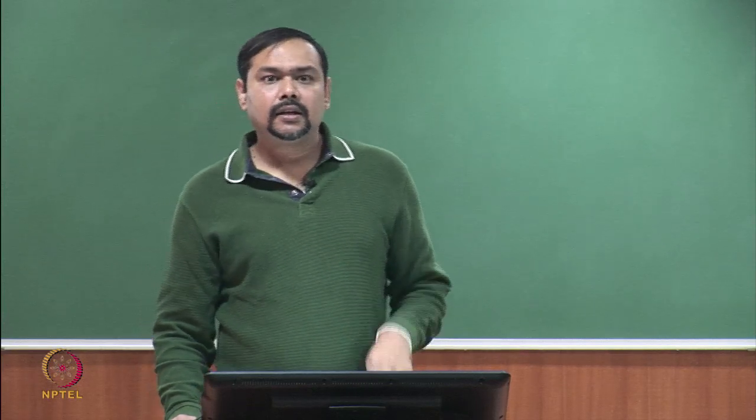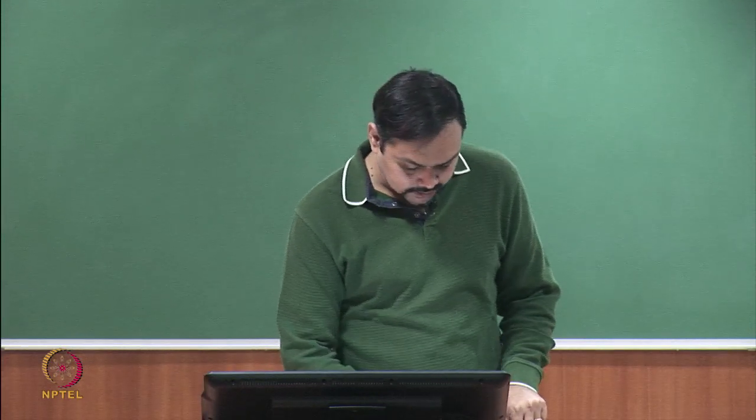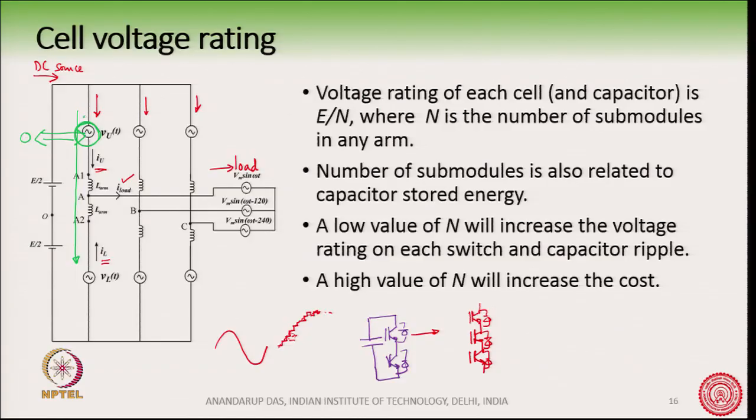The origin of this second harmonic can be understood from the fact that this voltage source here is a single phase voltage source and a single phase current is flowing. Note that these six single phase voltage sources are completely independent of each other; they do not even know that there is a lower arm.